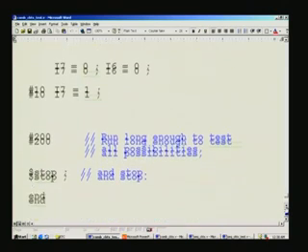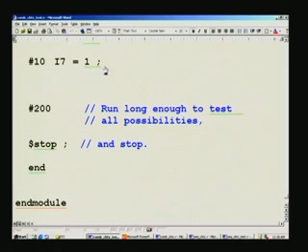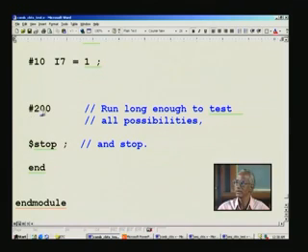So 140 nanoseconds, right. So it has taken so long. How much more cushion do we give there? Since this is a combinational circuit, you do not have to give much cushion, maybe 20-30 nanoseconds would suffice here, but still you can play safe, right. It may be required in sequential circuits, as we will see right now.